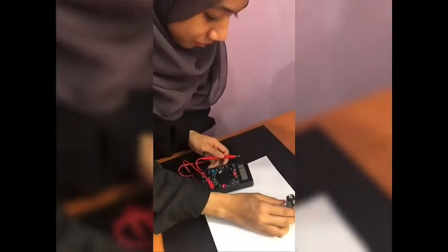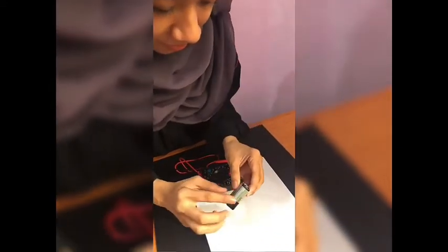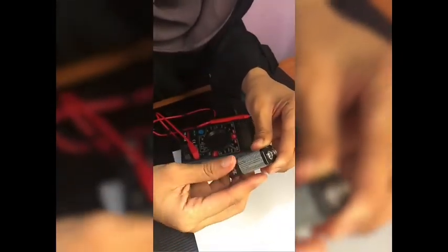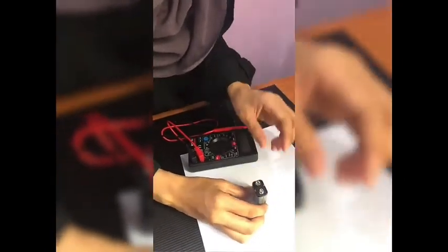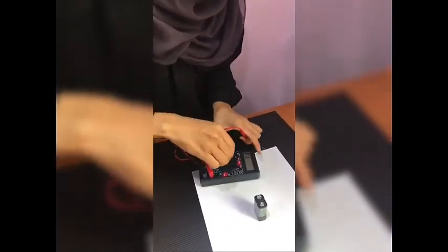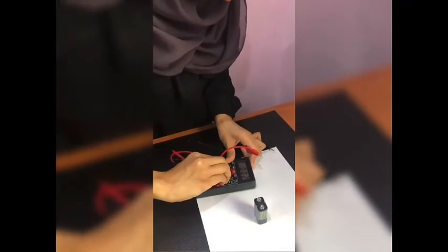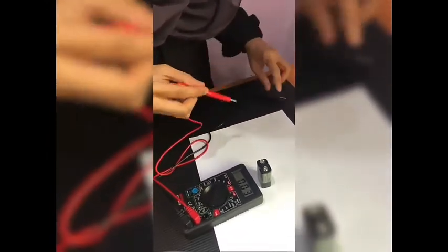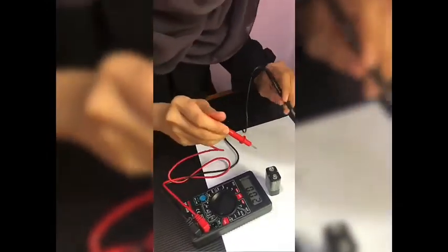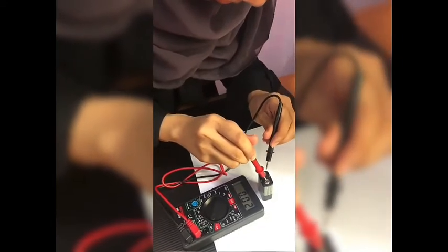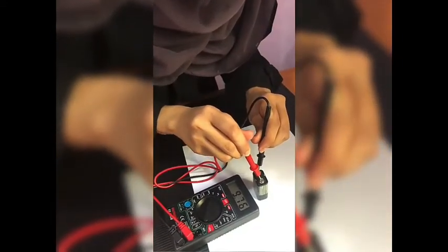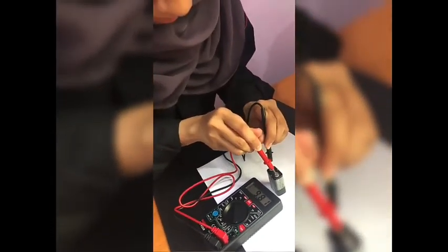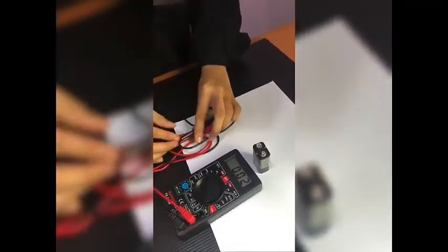Next, I will measure DC voltage. I use a 9 volt battery, and we have the positive and negative terminals of the battery. Next, simply turn the selector dial on the multimeter to the DC voltage setting. If measuring a single battery cell, then you can start by setting the multimeter dial to 20 volt. After that, use the two probes to measure across the battery terminals. In this video, the black probe is on the negative terminal of the battery, the red probe should be on the positive terminal of the battery, and the voltage of the battery will show on the multimeter display.